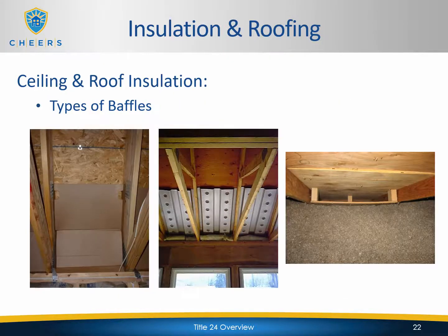And these are examples of baffles that you might see in the field. On the left-hand side, it's a simple cardboard baffle. In the middle example, those are actual baffles built specifically for that purpose. So it's a product that is bought and installed for that specific purpose. And then on the right-hand side, it looks like field-fabricated baffles, literally some cut 2x4s and plywood to keep the insulation in place and keep it from covering the vents. Each one of these examples is perfectly okay, as long as it's doing what it's supposed to be doing.